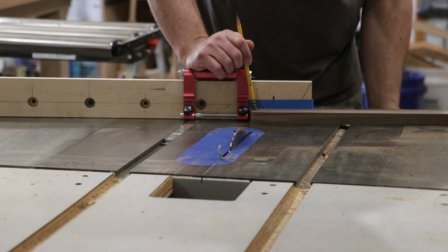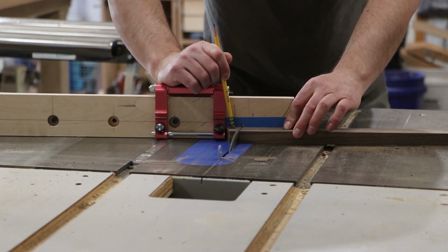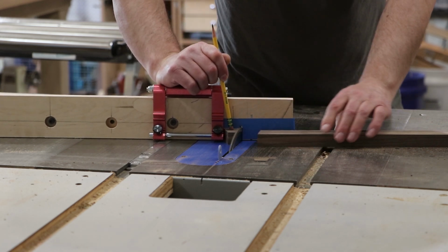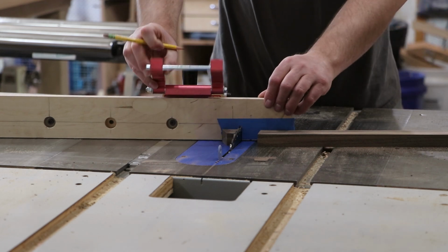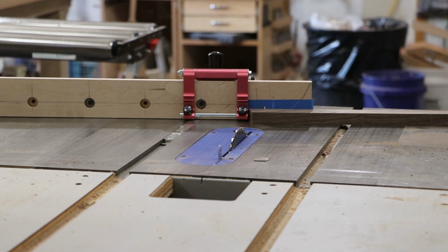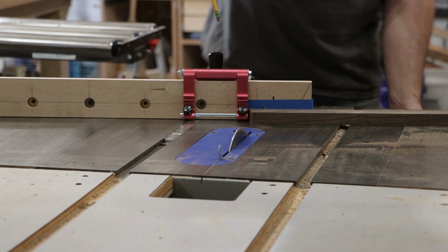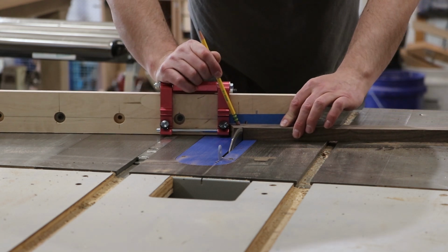All right, so now when we're out in the shop, we can set a stop at the miter gauge to set the exact length, and then set the angle of the miter gauge to the exact angle. And then I'll leave that stop exactly the same for all 4 cuts, because remember, each quarter is exactly the same, so you're going to need 4 of each segment. And then I'll just reset between each segment that I need.